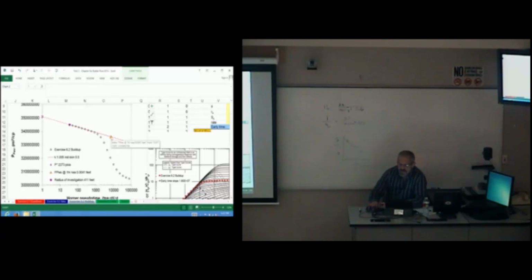Seems to me, Grady, that I had some point to make on that I didn't, but we'll get to that. Okay, now the additional thing we can get on any buildup, whether it be radial flow or linear flow, is an extrapolation, because Horner time is constructed so that at infinite shut-in time, the ratio becomes 1, so we can extrapolate the linear section to a P star. And I think almost everybody got full credit for P stars. It seems like everybody was really good at that.